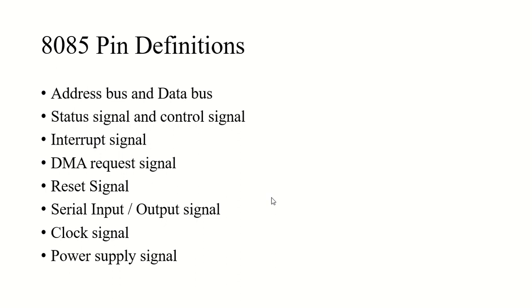Don't worry about the wordings. If you don't understand, we will be using it when we go through the machine cycles and different instructions. So for now, just understand that when the trap line is activated, the microprocessor performs an internal restart automatically at the address 0024 or whatever address.